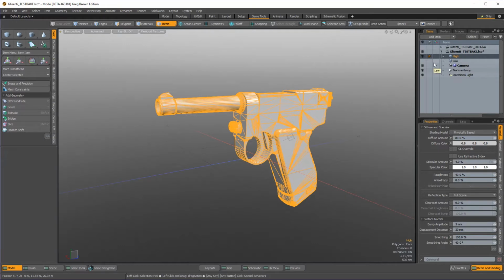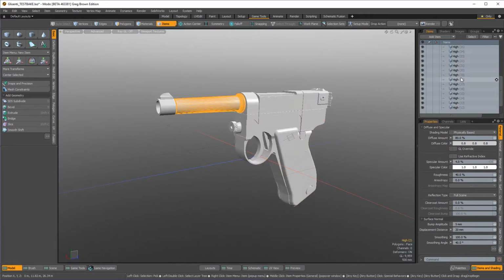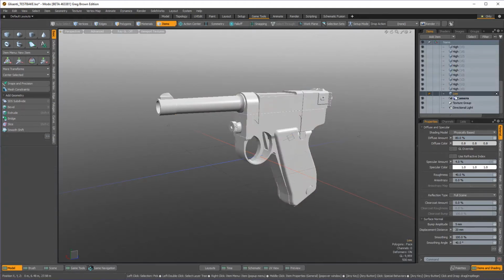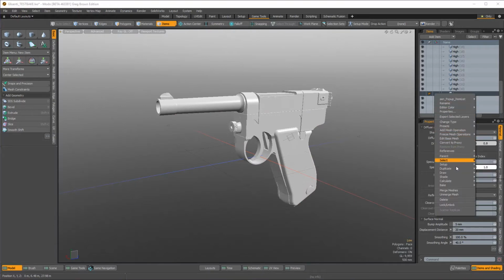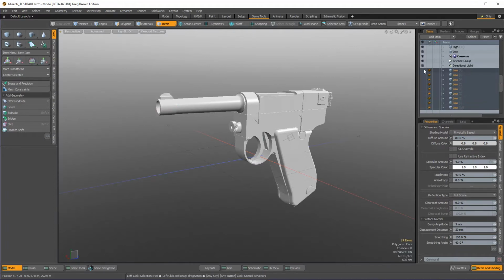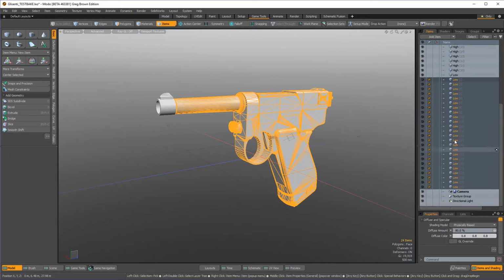So let's right click on our high mesh and unmerge this mesh. We are separating the mesh out into all the various parts that have not been welded together. And this allows for much easier exploded baking. And do the same with the low and go to unmerge mesh. I'll go ahead and turn that on. And let's shift select everything. Did I get everything? Yes, I did. And drag that on up and give myself a little bit more room.